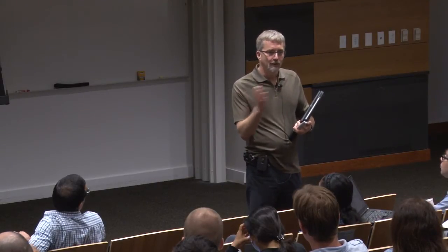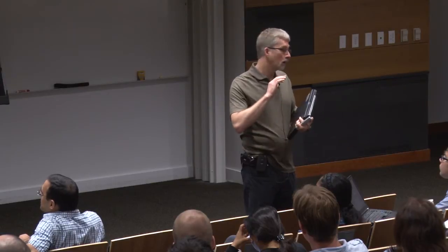No, it's in my PD controller. So remember that robot was supposed to deliver 60 amps of current to each motor, but they're currently limited at 30, right? So by the time you go through the harmonic drives, I've got maybe 110 Newton meters, but I've got stiction giving me a backlash effect. So my tracking errors on my joints is where I'm having a problem. No, the resolution is down to the micro degree, so I can see all of my error, but I can't do anything about it.